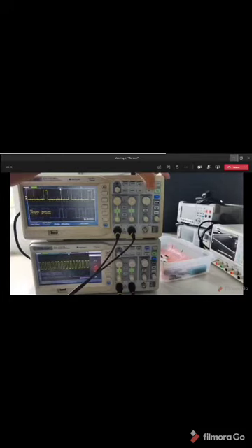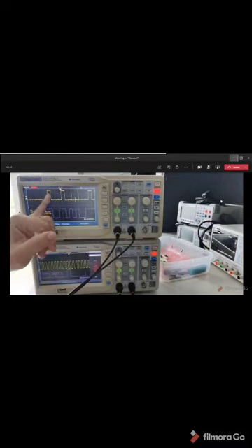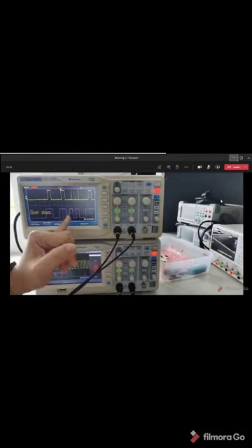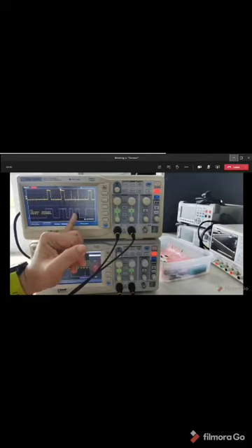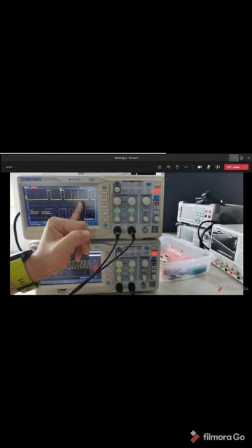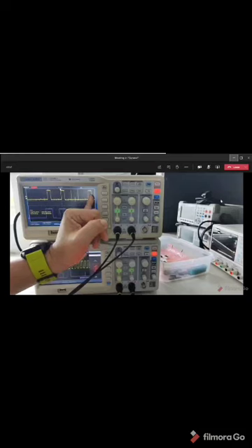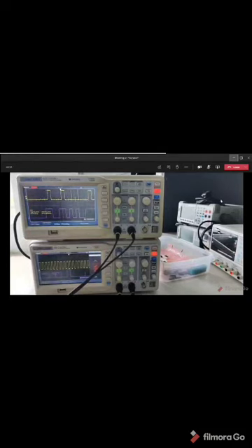So we have detected 0 1 1 using the flip-flop and the circuit from our part 2. So that is the part 3 for us, but the problem is we are getting a lot of extra spikes that are known as the false outputs.